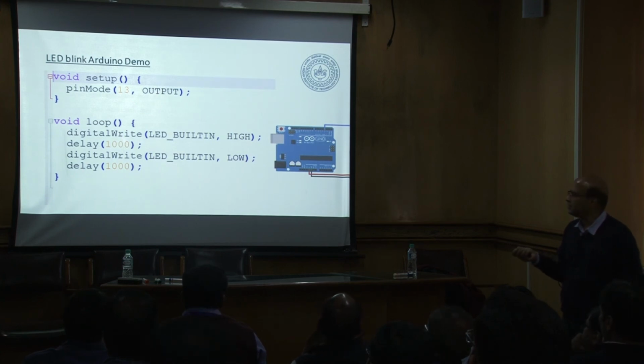Then we say digital write, LED built in, which is this one, and we say high. Then we give a delay of something. Then we give LED, so LED built in is again an internal function.